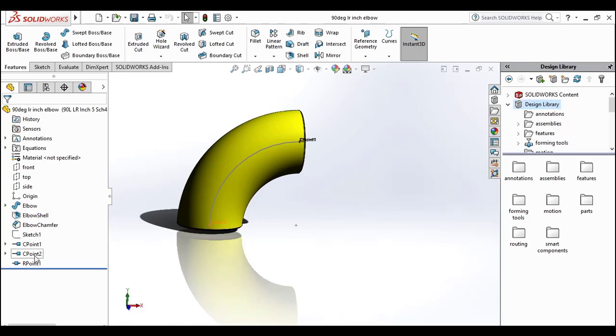After you highlight each one, you can see it appearing in orange on the screen, so you can better identify which point is located where. At least one end of this pipe has to be connected via a connection point in order to be considered part of a route. These are crucial to making sure that your route is continuous as you create the pipes.